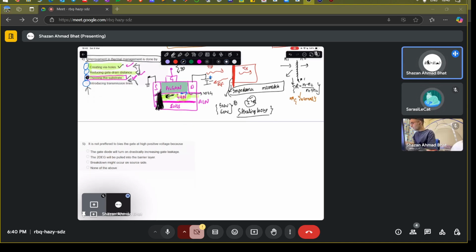And again, going to the other reasons, this particular distance can also help in thermal management, because heat is produced whenever you apply a high RF signal to the gate voltage. So there is also a heating region near this particular area.